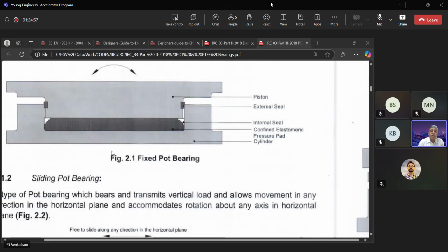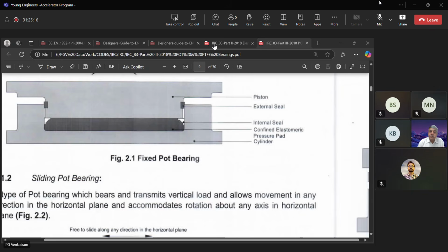Even if the grouting at the base is only partially done, the elastomer disc will expand slightly. It will have non-uniform pressure. All those will happen, but it will not lose its rotational capacity. So that is why the elastomeric bearing is more forgiving.